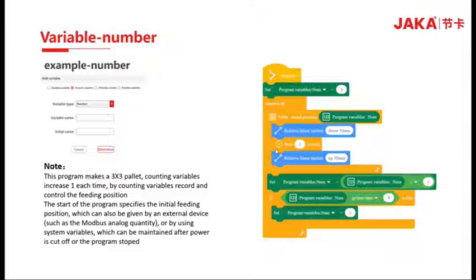After making the up-down movement in the palette, the robot will set the numerical value to +1. Variable equals variable +1. Then the instruction here will be ignored, because it's not greater than 9. Then the robot will make a loop and pick up the parts until we reach 9. When the numerical variable num is greater than 9, it will reset the variable to 1. And then it will start the movement again.